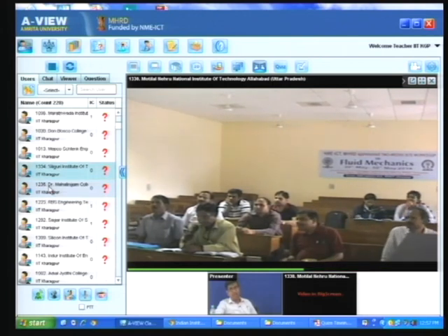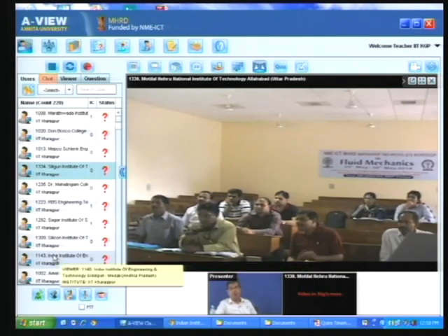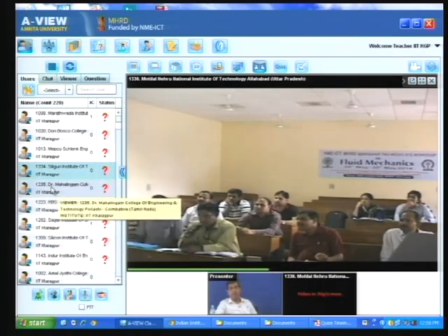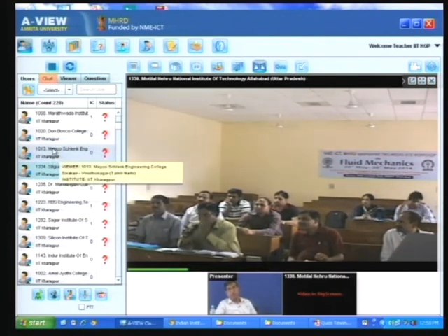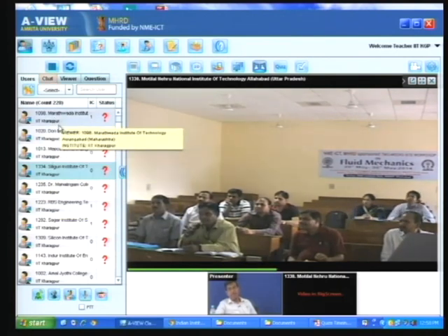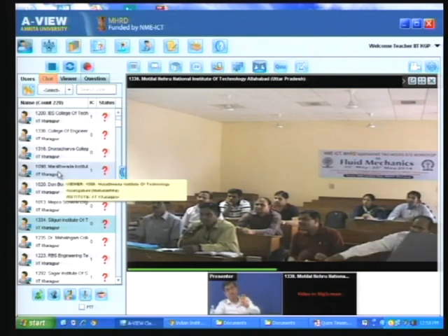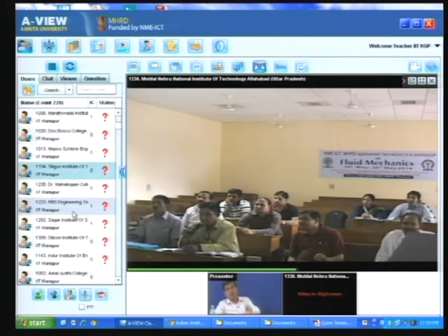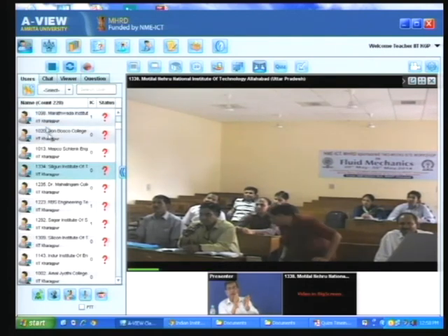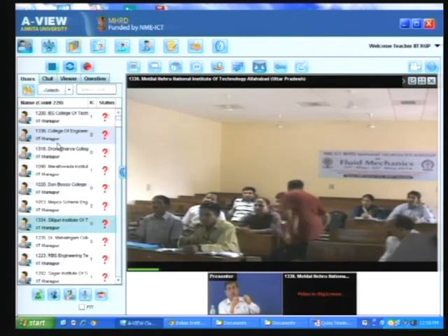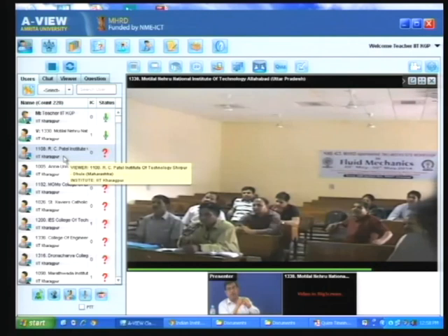No, this is not derivable from Rayleigh's indicial method, it is derivable from other theory or from experiments. Exact solutions from the Navier-Stokes equation for laminar flow are derivable, but Buckingham's pi theorem and Rayleigh's indicial method only give you the number of pi terms and what grouping of the dimensional variables will be a pi term.